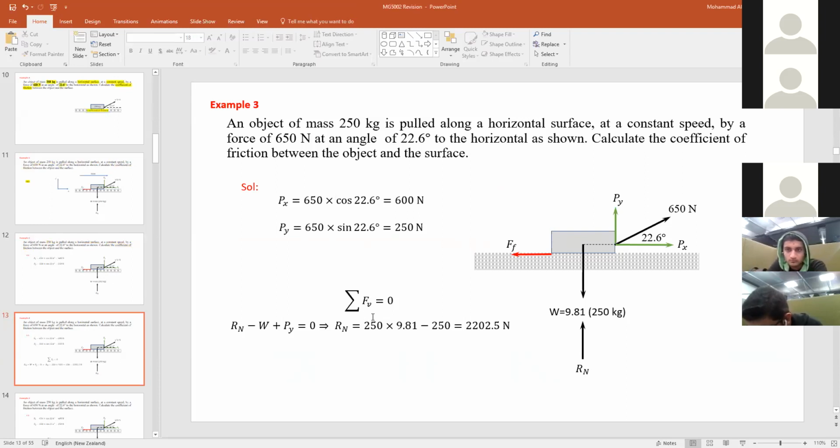If we write the equation for the summation of forces in the vertical direction, the y, what do you have? You can see all the forces going upwards, so I can take this arrow and put it next to this to represent my vertical direction. It's very important to add these components to your drawing, because you are telling the person reading after you: this is my vertical, I'm going with every force going in that direction. Going upwards is positive, and a force going downwards is negative. That's very, very important.